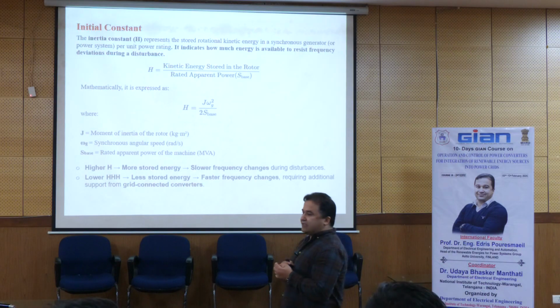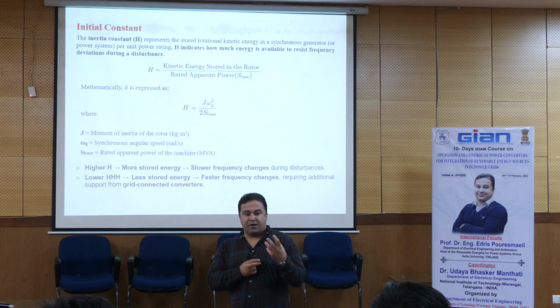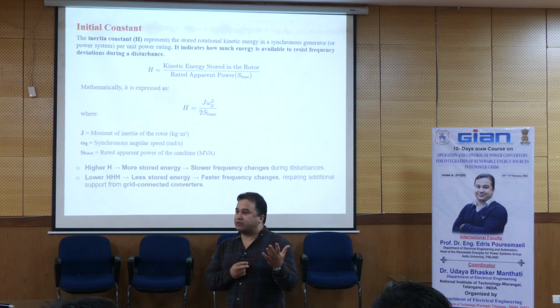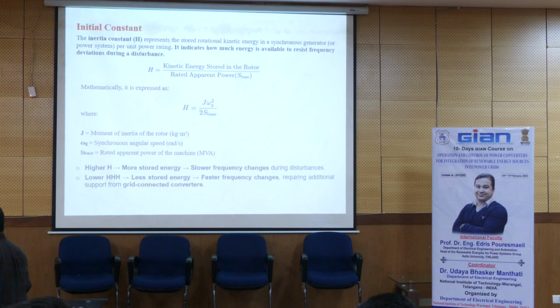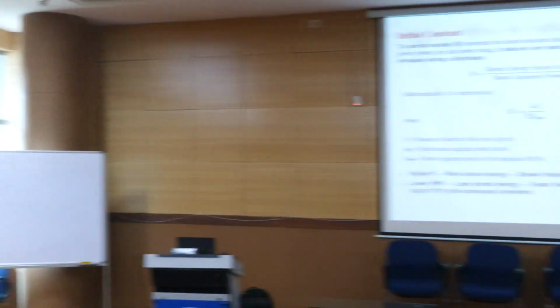But again, returning back, can anybody easily say what the unit of H is? The unit of H is second. Okay. So it indicates that in an abnormal situation, the machine transfers energy for that many seconds.